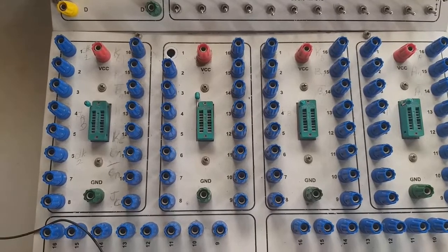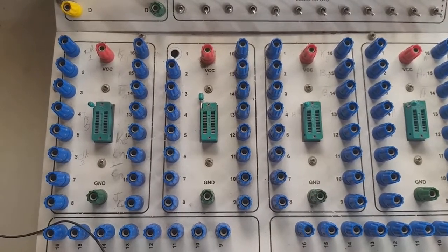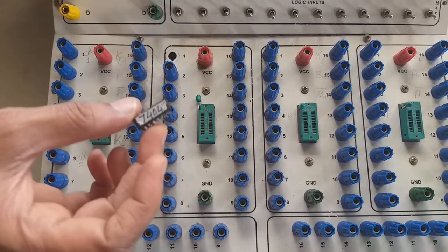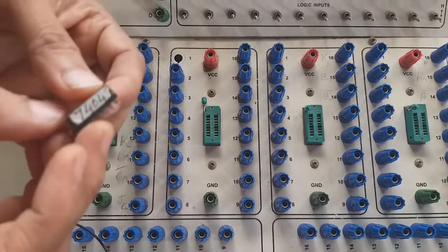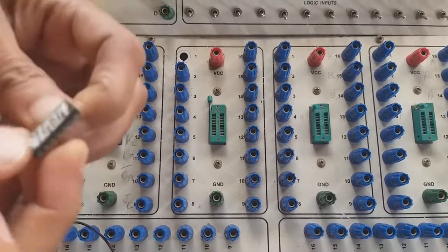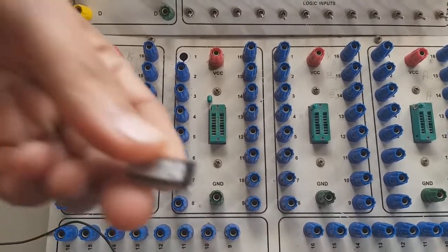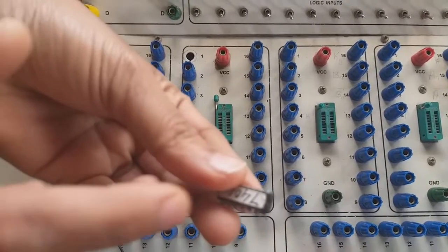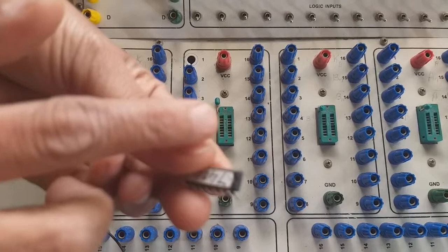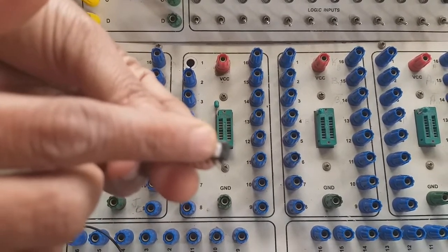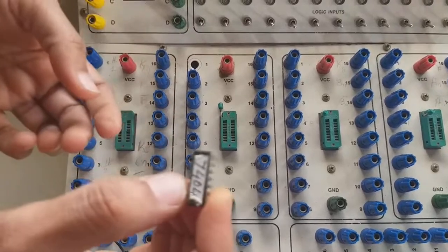So, now we are going to realize the NOT gate. So, NOT gate IC number I mentioned, it is 7404. So, this is 7404. So, here in this IC, you have a small notch at the top. Okay, you have a small notch. Here you can see the small notch over here. Okay, small notch, that should face north side. Okay, that should face to the top side of the kit in other sense. Okay, keeping this in this fashion.